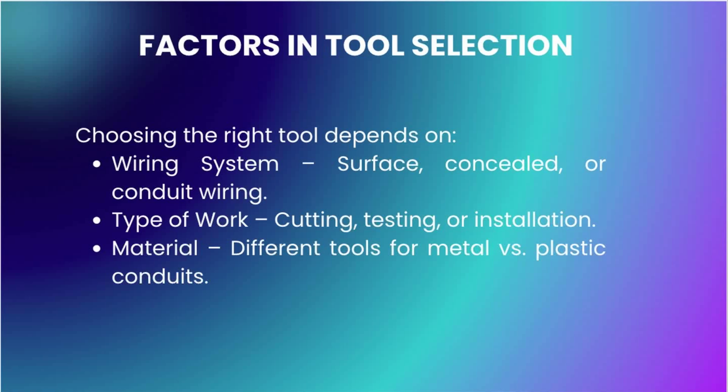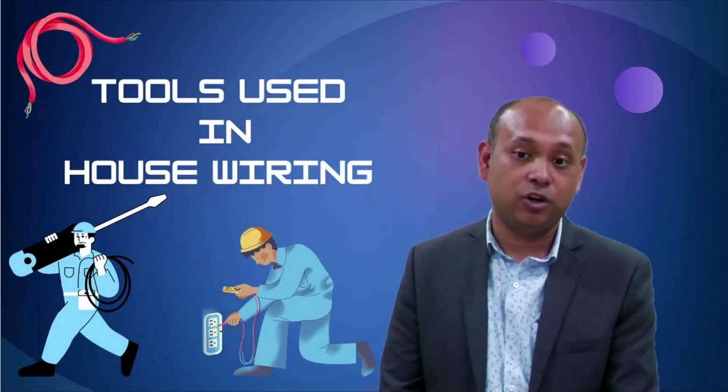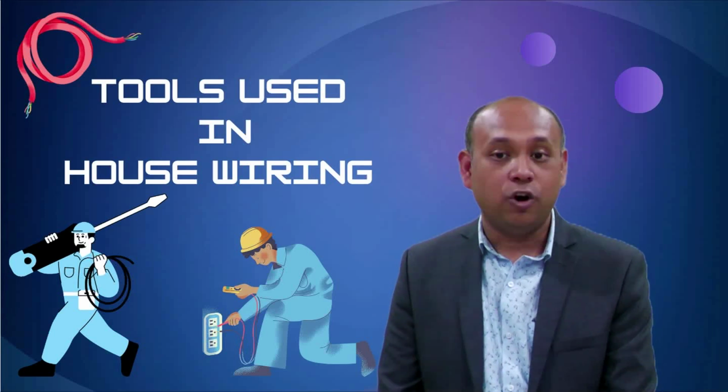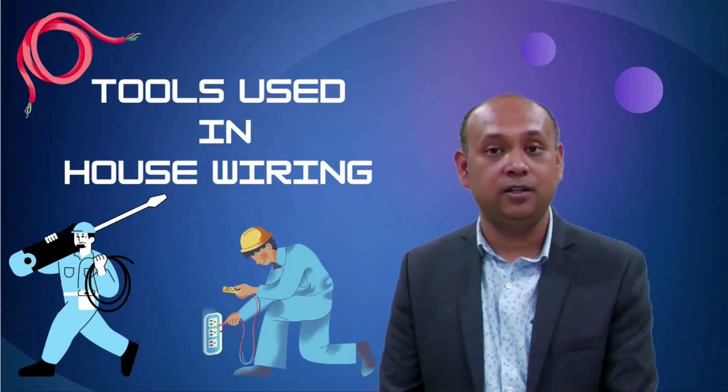The choice of tools also depends on the material type. Metal conduits require specialized saws, threaders and bending tools. PVC conduits can be cut using standard saws and shaped using heat. Brick or concrete walls require powerful drilling and chiseling tools.